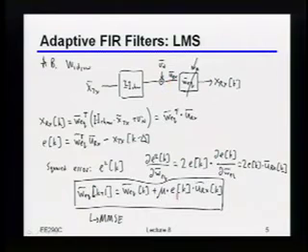So in other words, this E of k, even though it's the instantaneous value, I want to know how much of this error came from the previous bit. How much of that error came from the bit before it? How much of the error maybe even came from the bit that will follow due to precursor? So when you do this adaptation here, just like when you did it in MATLAB for the MMSE, you do have to line up all of those vectors relative to each other to make sure that you're adapting the right coefficients. Does that make sense?